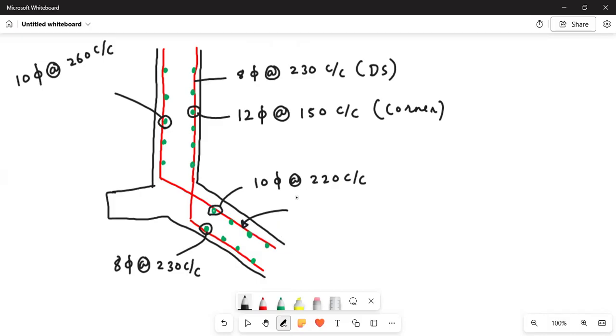And you have provided reinforcement at both faces of the sloping slab. So at both faces of the sloping slab, the reinforcement is for the direct tension, and that reinforcement is 8 phi at the rate 300 mm center to center. This is what you got. Okay, so we have completed the design of the square bunker.